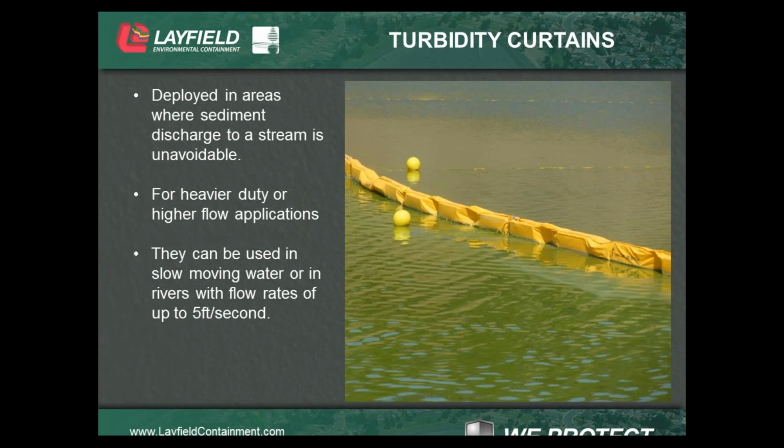In addition to that, they're a lot heavier duty, used for higher flow applications. So if you've got a lot higher flow in streams, or you've got tidal action, that's where you're really going to look at utilizing a turbidity curtain as opposed to very low flows or standing water. Turbidity curtain is also going to be a longer term solution. It's going to be in place for a lot longer than a floating silt curtain would.